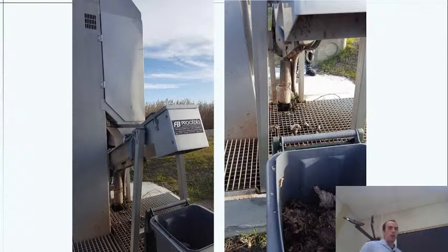So here, the influent to this wetland system, we first have some sort of a screen chamber bar rack system to take out the large particles, large scraps of things that were flushed. It's a bit of an automated system, and you see it filling up this trash bin here with junk that's caught in the wastewater, so it doesn't enter into the wetland system.